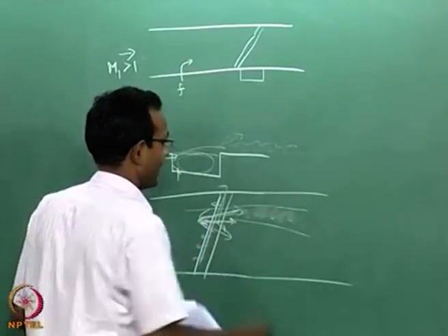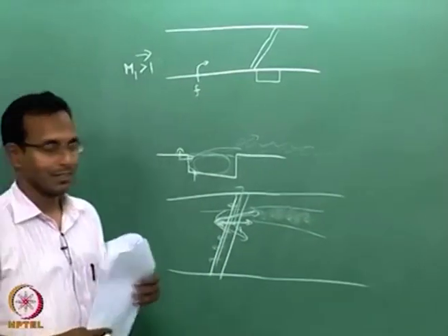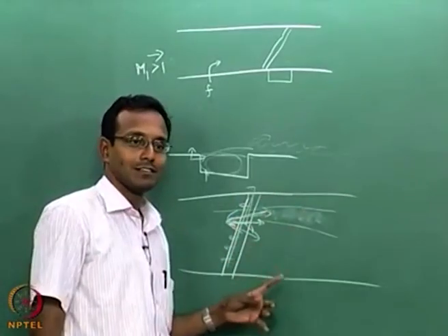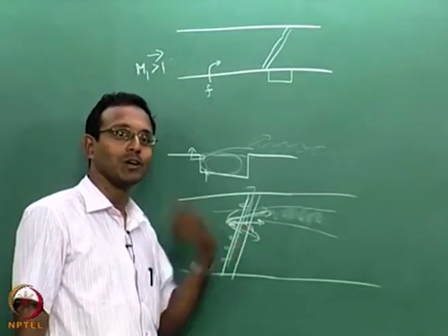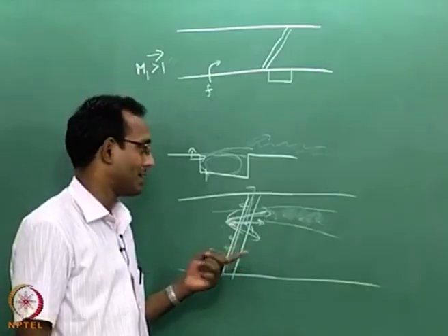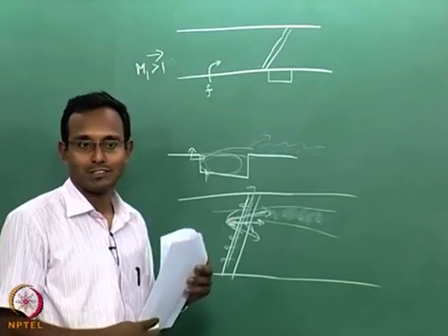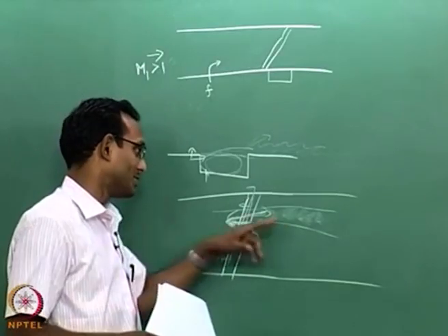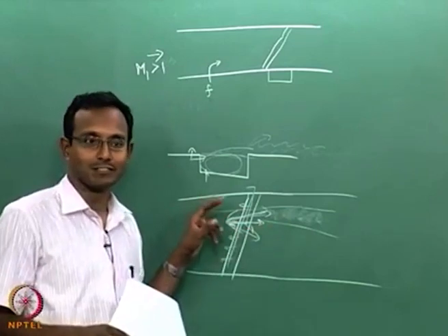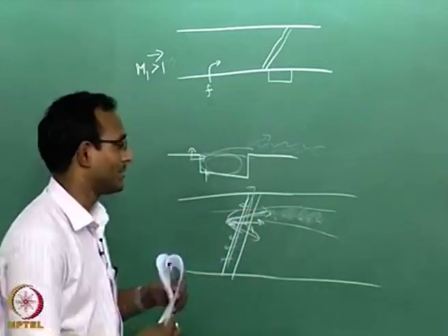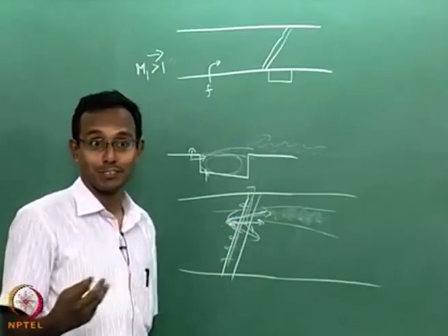When it is burning, again I am adding heat to the system. If I am adding heat to the gas, I am again going towards M equal to 1. Another reason for thinking about thermal choking. Now this is thermal choking, and there are other things where P naught decreases, so it is typically friction choking or mixing based choking or mass addition based choking.